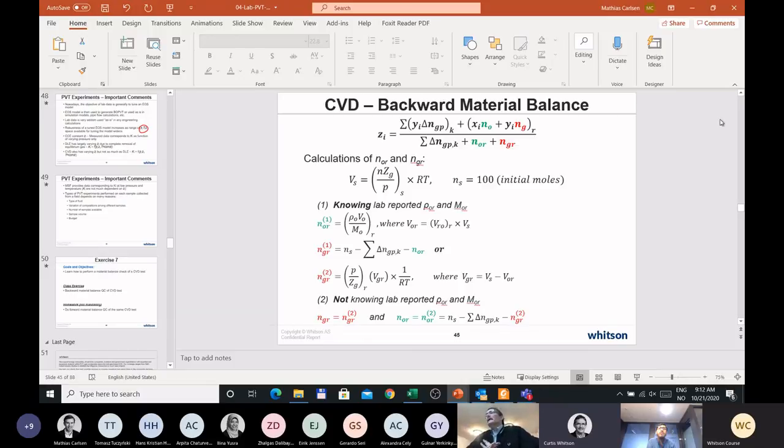So another way to get that data is that you just do 2 or 3 or 4 recombinations of separator samples, for example, and CCEs of those mixtures. So I would take any day of the week 4 recombinations of separator samples with the CCE of each over a DLE any day of the week. Probably even the CVD test. Because there, the uncertainty in compositions is very small.